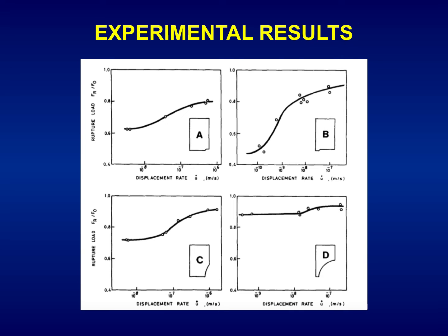On the other hand, in the right-hand side part of the plot, we have the quasi-instantaneous test, in which even for this quick test, we have a deleterious damaging embrittlement effect of hydrogen due to the achievement of the boundary condition for the hydrogen diffusion problem in the sample.